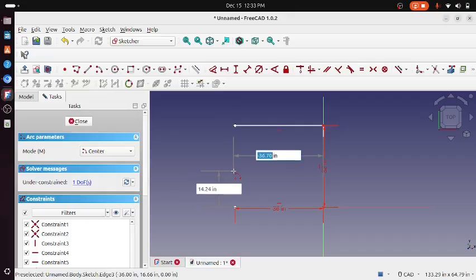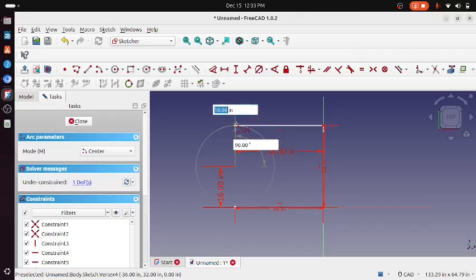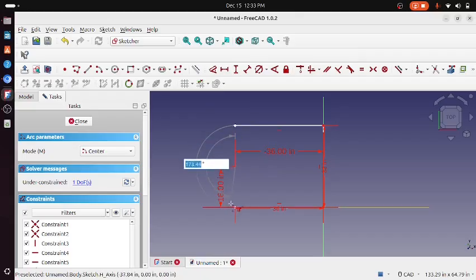Now please, if you're going to copy this exactly, what this is going to do is put the x coordinate, which is at the top right there, in negative. So it's going to be negative 36. Then tab, that's going to be 16, because we want that in the center. And the center of 32 is 32 divided by 2, which is 16. So click. Now I'm going to go up with my mouse, and I'm going to left click. Make sure it says 16 though at the top. So click, and then I'm going to bring it down like this. And I'm going to go to that white dot once again and make sure it says 180 degrees. Click.